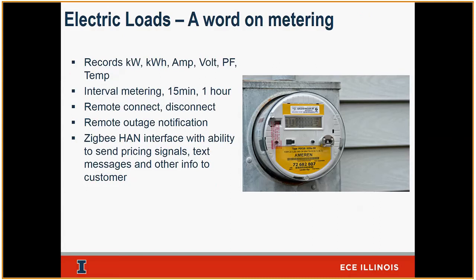Then they moved up a notch, and they changed these meters to automated meter readers. So you stopped sending people out in the field. We call that AMR, automated meter reading, right? So we stopped sending people in the field, and we changed that meter with one that has a chip in it, and it'll send you its kWh value once a month. So you'll read that. You don't have to send anyone into the field. You started billing people off of that, right? So that started going in our database, and we started knowing a little bit more about our data.